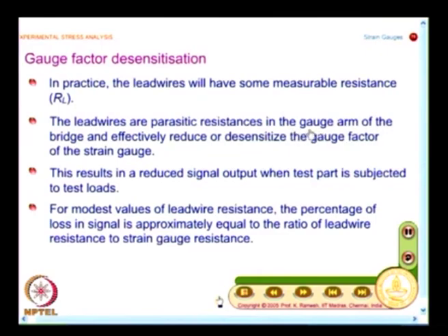You do not want them, you want to have a magic material which has no resistance and the strain gauge is connected. See, I also said, if you have a magic material, a single speck of it can have 120 ohms or 350 ohms, I paste it at the point of interest and connect it and make measurement, then I have no problem about strain variation or gauge length influence, etc. And we saw it is just not possible.